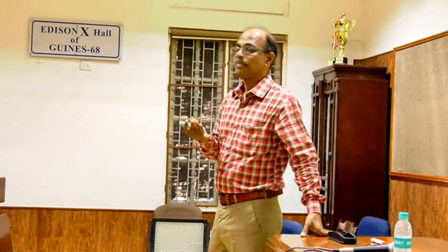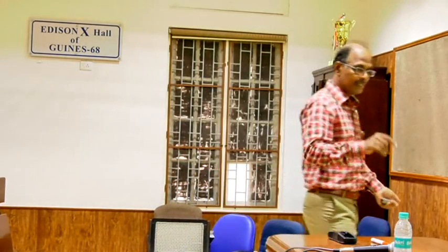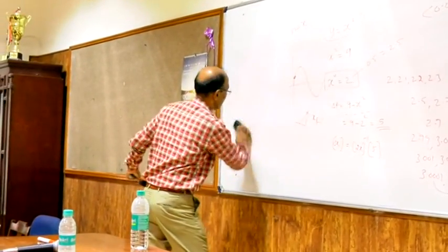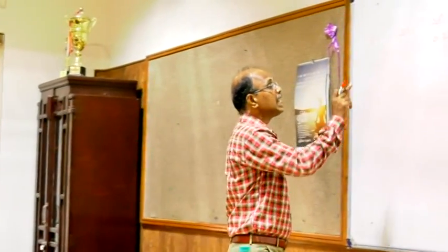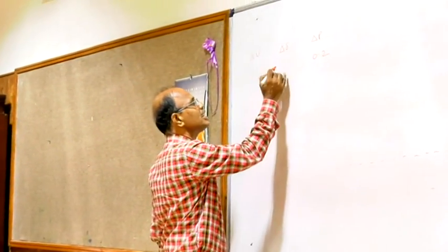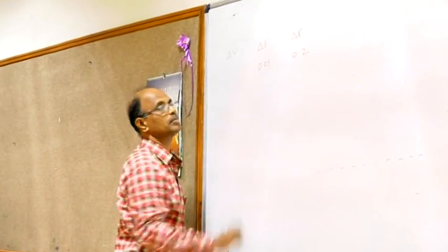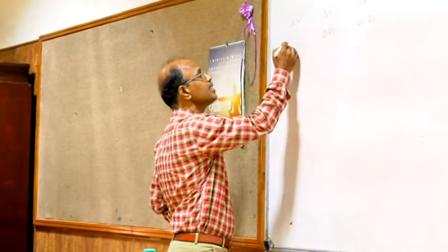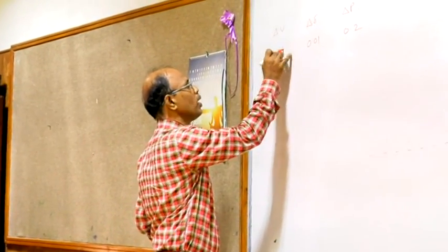the feature used is decoupling, decoupling between the P and Q equations. In general, if you make a small change, that will cause a large change at this point. The change in angle may be 0.01, whereas the change in voltage will be 0.001.